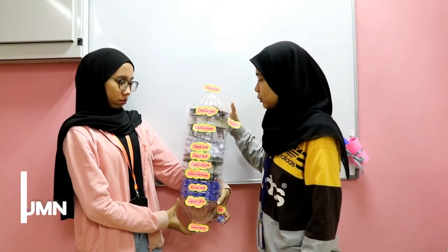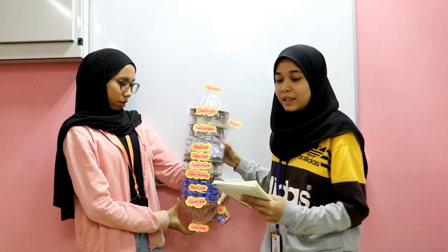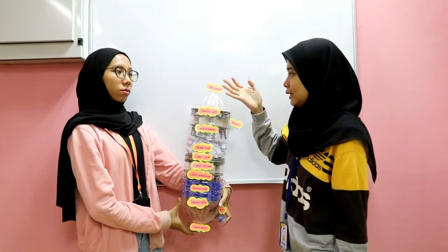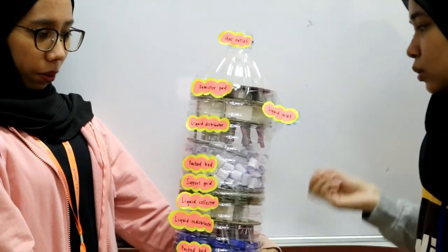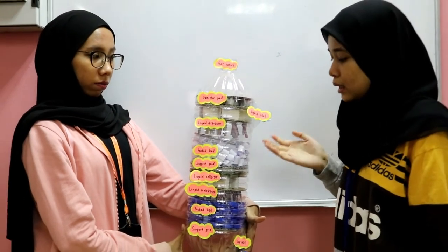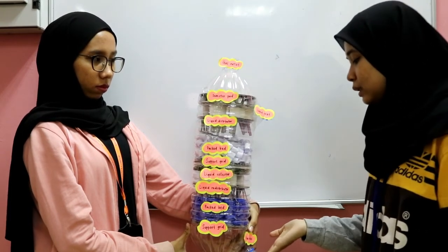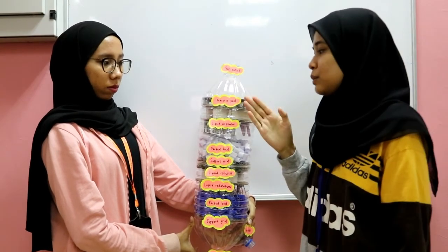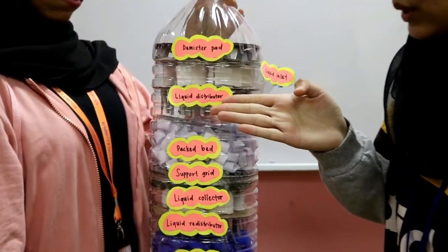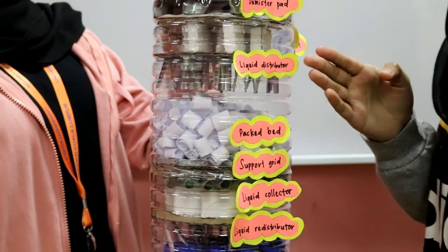So I will explain about the model we made with my teammate, which is the packed absorption column. This is the gas outlet, liquid inlet, liquid outlet and gas inlet. The liquid will enter at the liquid inlet and go out at the liquid outlet, and the gas will enter at the gas inlet and go out at the gas outlet. The upper layer is the demister pad. After that, this is the liquid distributor, and the type of liquid distributor is a flow multiplier distributor.